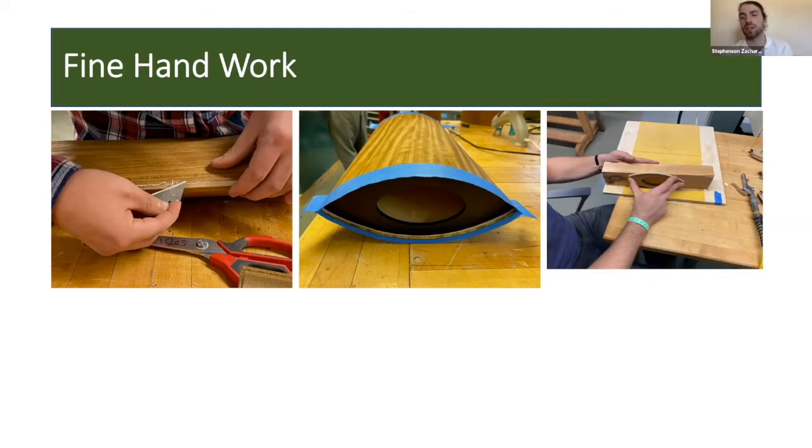And the final picture depicts us sanding off the edges of the bases, because after they come out of the laser cutter, they have that charcoal edge, and wood glue will not stick to charcoal. So we pretty quickly figured that out and just sanded off the edges to give it veneer against MDF rather than veneer against charcoal.